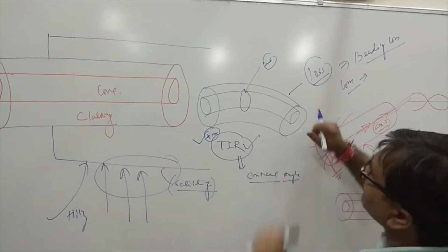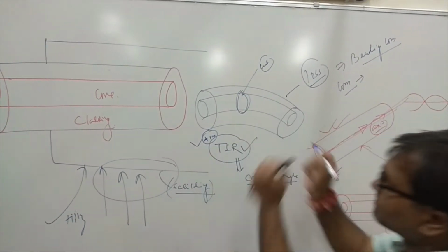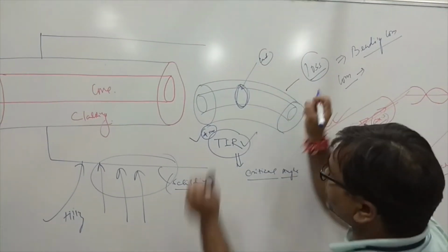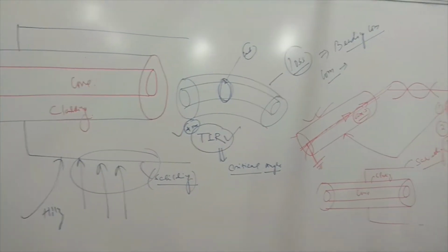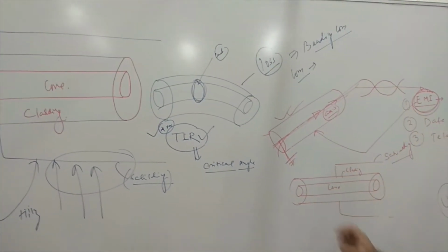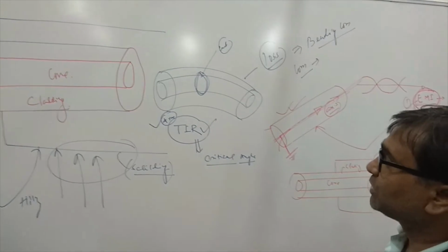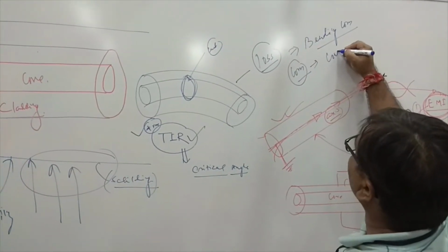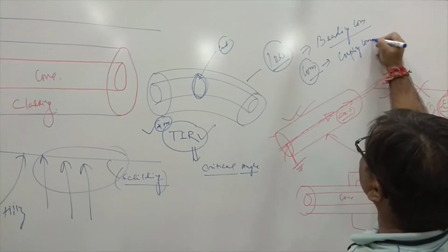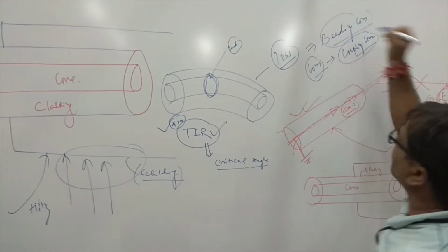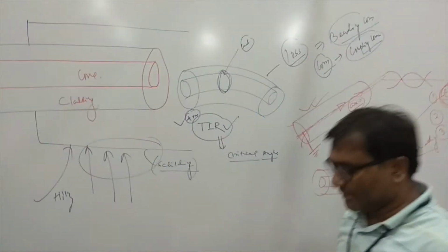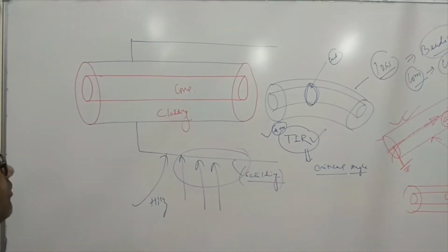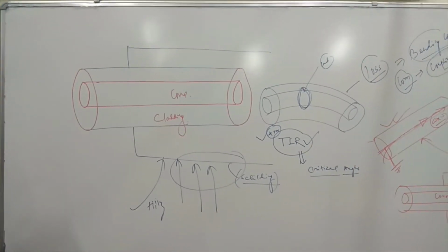After the cut appears, we do coupling of the fiber. Coupling is the phenomenon where two mode field diameters are combined through the splicing technique so that loss can be minimized, and the loss due to the coupling is known as coupling loss. I will explain later. This is not the right time to explain bending loss and coupling loss, but this is the phenomenon. So what the core, cladding and shielding are is really important.